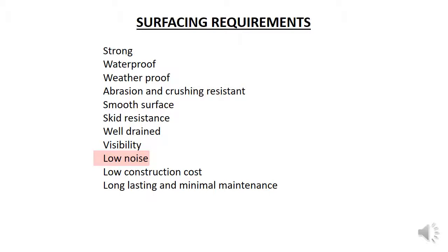Noise from the road also needs to be considered. Coarser surfaces cause more road noise, which can be a problem in urban areas close to high-speed or busy roads. At speeds above 50 km an hour, the main noise from cars is the noise of the tyres on the road, as opposed to engine noise.